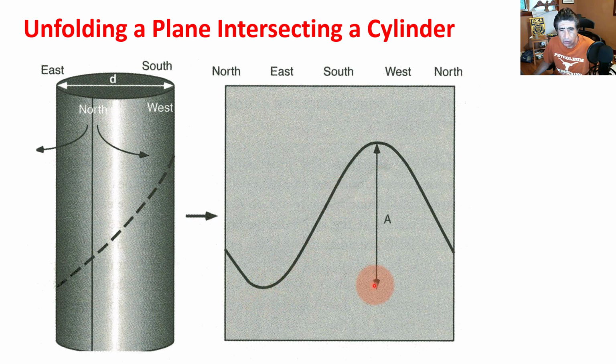The amplitude is directly related to the dip of the formation. So the larger the dip of the formation with respect to the borehole axis, the larger the amplitude A. And the azimuth, which is also another way of calling strike of this plane, will be based on the locations of the peaks and troughs. So bear that in mind when we look at images, please.